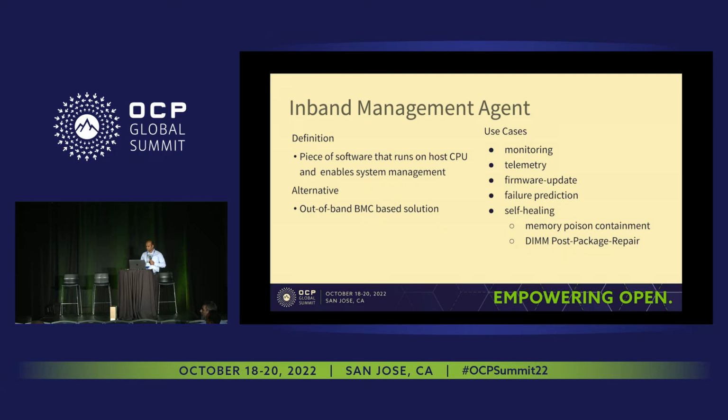DIMM post package repair is a very interesting concept. In order for us to do the host-based approach, we need physical address information. That means somebody has to do the translation of host address to physical address. What is the thought process in this design architecture? Will the translation be done by the host, or will we have to call some other service to do the translation? So you need code that can do the translation. It's exactly as you mentioned, it's vendor specific and hardware specific, how the addresses get mapped. But assuming you have code which can do that, it typically runs in band.